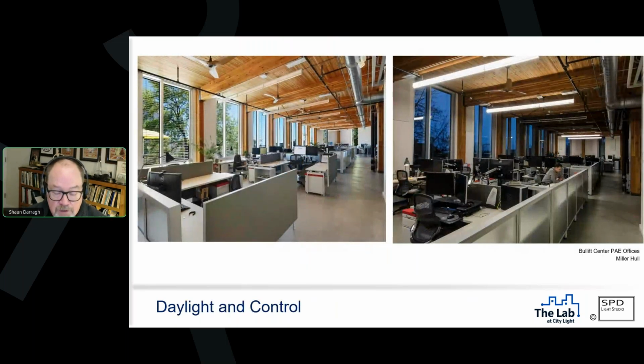Okay, make sure you have daylight controls, right? So this was my office in the Bullitt Center. Same space, but at night, during the daytime, the lights are dimmed way down, right? At night, when Tony is here working on a Sunday afternoon, when I'm in here taking this photograph, and Mitri is down working down here, you'll notice that only the lights that are around them are on. Everything else is turned off. Critical.